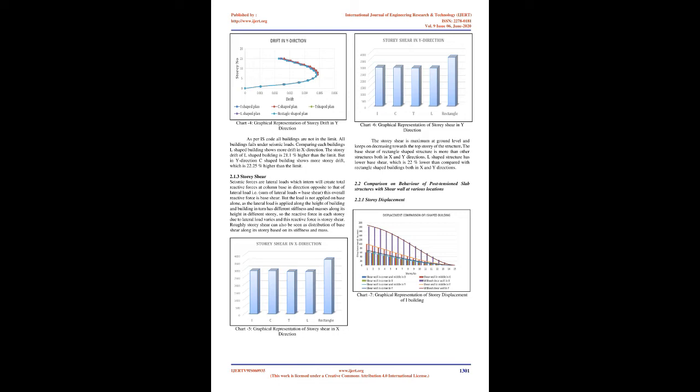2.1.2 Storey drift. Storey drift is defined as the difference between lateral displacements of one floor relative to the other floor. Total storey drift is the absolute displacement of any point relative to the base. As per IS 1893-2002 clause 7.11.1, the storey drift in any storey due to the minimum specified design lateral force with partial load factor 1.00 shall not exceed 0.004 times the storey height.